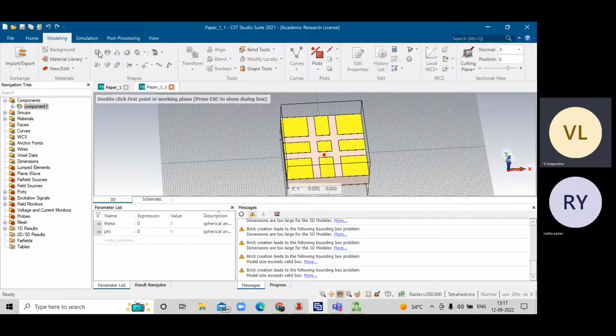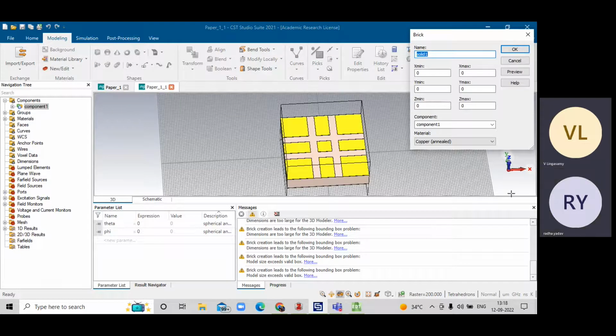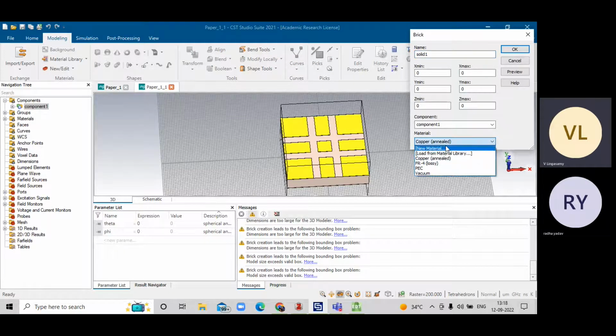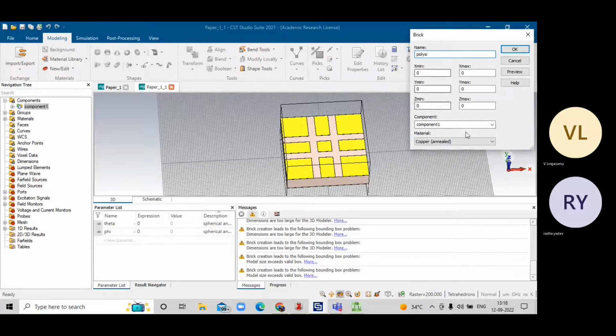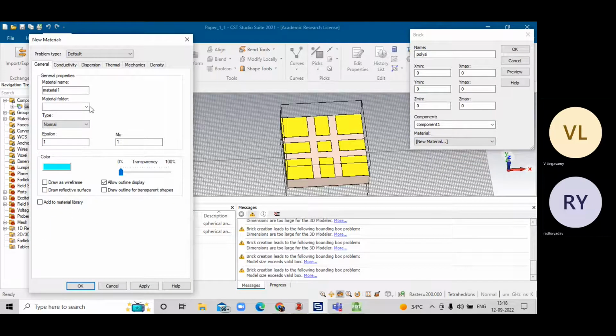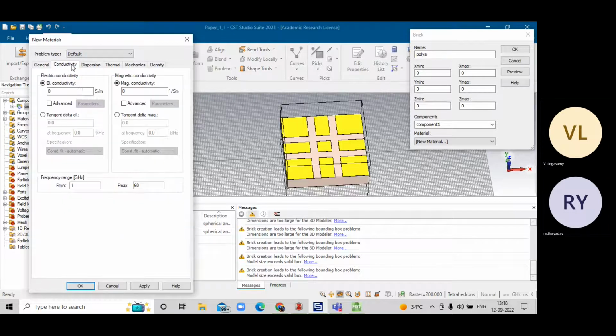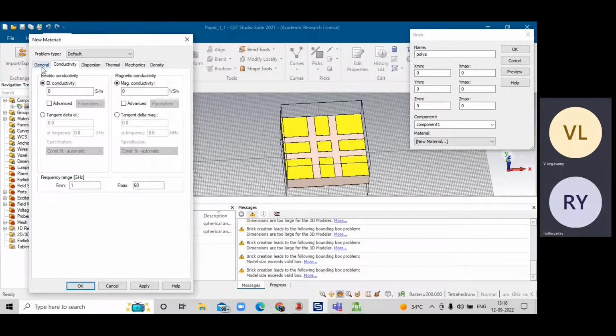No problem. See, loss tangent will not have much deviation, unless in the matching and all, much deviation will not be there. Only the attenuation part will have something. So dielectric constant is the main parameter basically. Sir, conductivity is also required? Conductivity is okay, no problem. Because conductivity you don't know, right? And if you know the dielectric, then yeah, it's okay. No problem.